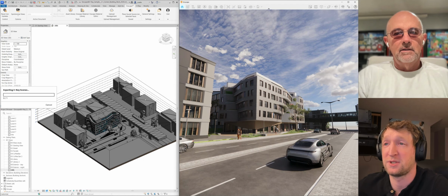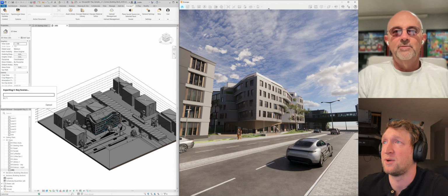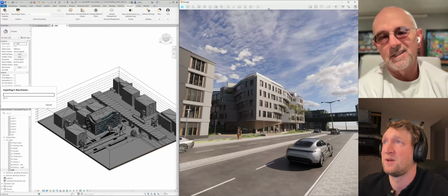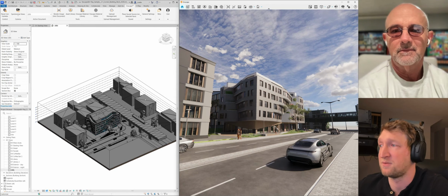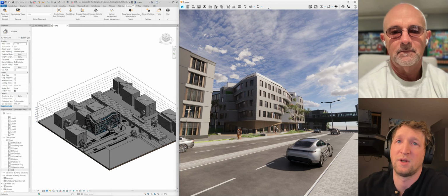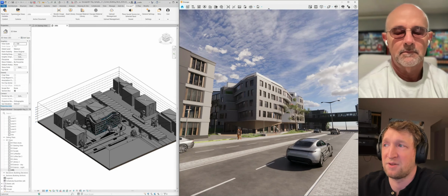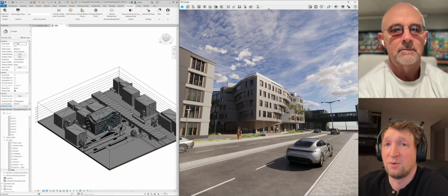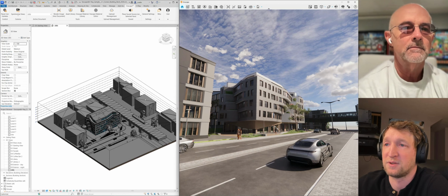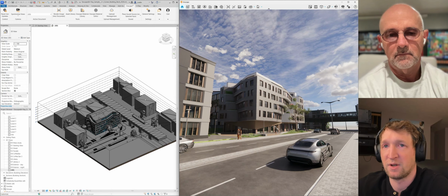And we're just simply going to hit export. We're going to go to our file that we want, and then we're going to put it in a good location. I set up an Envision folder. So we're going to select folder, and then we're going to export. Now what this is going to do is take everything that's visible inside of Enscape and export that. What's really cool about this is now for the first time you can bring your geometry out of Enscape and into Envision.